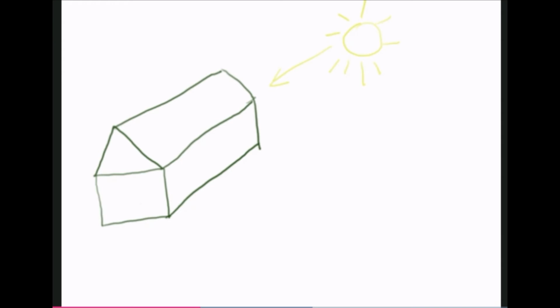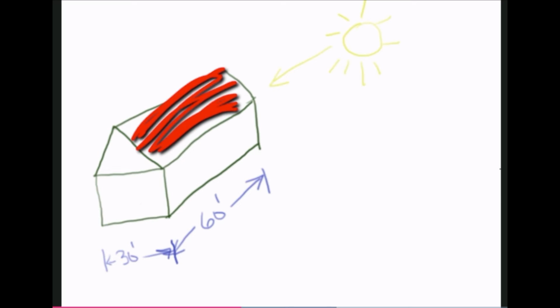We'll use trigonometry to figure out the roof area, as the roof is on a slope, but we'll start by taking the dimensions of the house, 30 feet wide by its length, 60 feet long, and work with the assumption that 1/2 of that roof area is south facing.